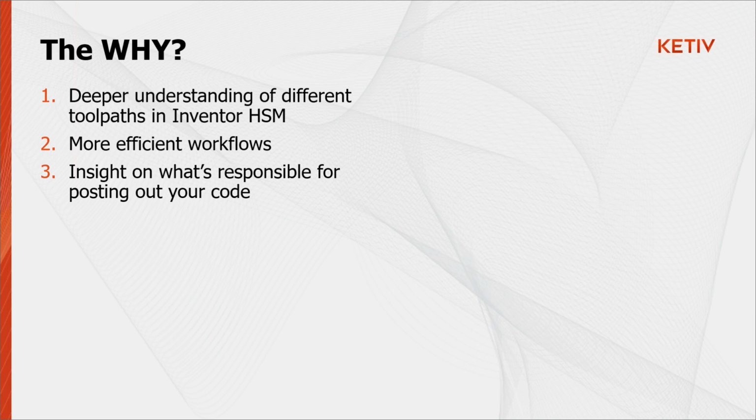And then lastly, we are going to be talking about the post processor inside of Inventor HSM, right? If you guys aren't familiar with the post processor, that's really what's taking the toolpaths that you program and converting them into a language that your machine is going to understand, right? So not all the machines are the same. And again, we are going to be covering what the differences are between some of these different post processors.